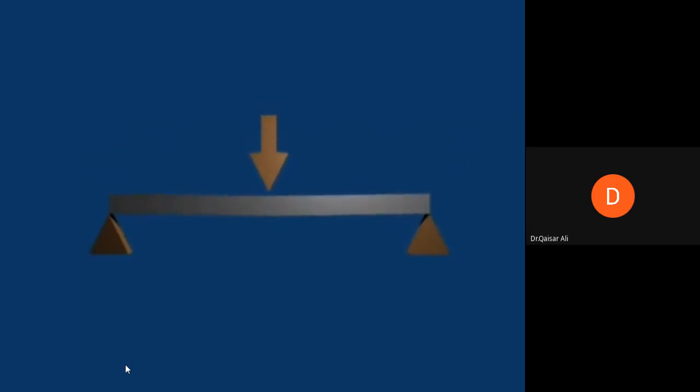This is now a beam subjected to flexural stresses by a point load. You can see tensile stresses are produced in the lower fibers and compressive stresses are produced in the upper fibers. So we need to reinforce the lower part, not the upper part. Flexural stresses are those stresses produced in a member when compressive and tensile stresses are produced side by side. Remember, they are called flexural stresses or bending stresses, because they are produced due to bending. You can see now torsional stresses being produced in a member. If such effects are produced in a member, they will induce torsional stresses, and the member must be designed against these torsional stresses as well.